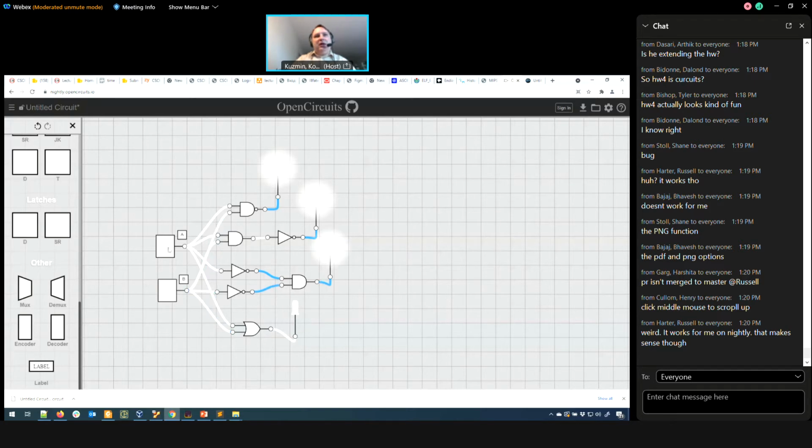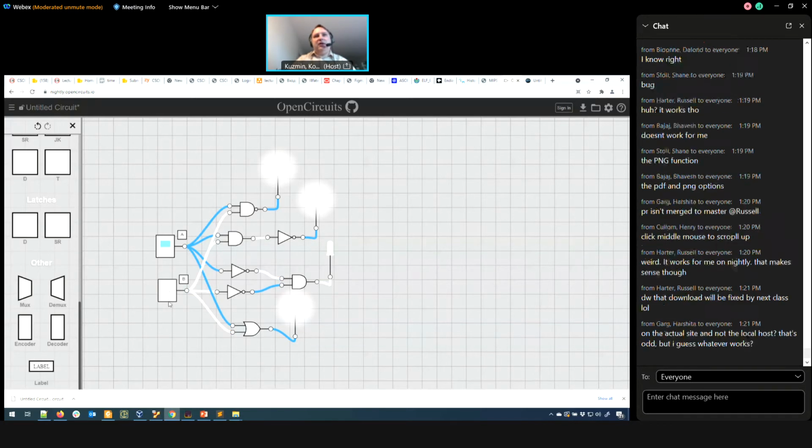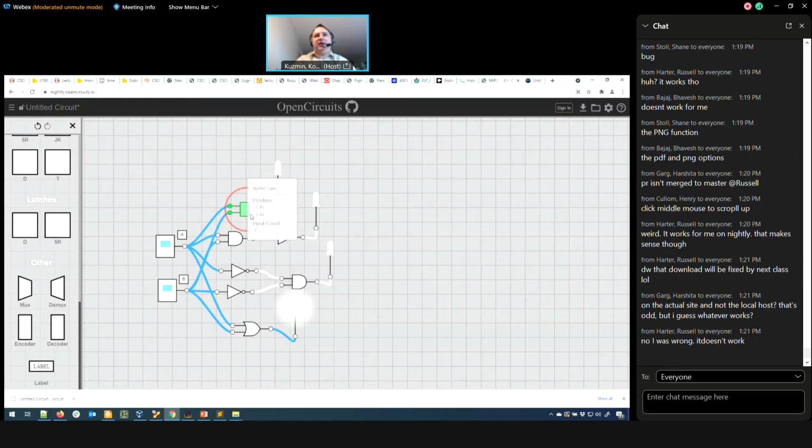And then we try this, they're the same, and then the fourth combination, 1 and 1, we see that they are off. Okay, so that's how we can see that this single NAND gate performs the same function as AND followed by a NOT, quite predictably.